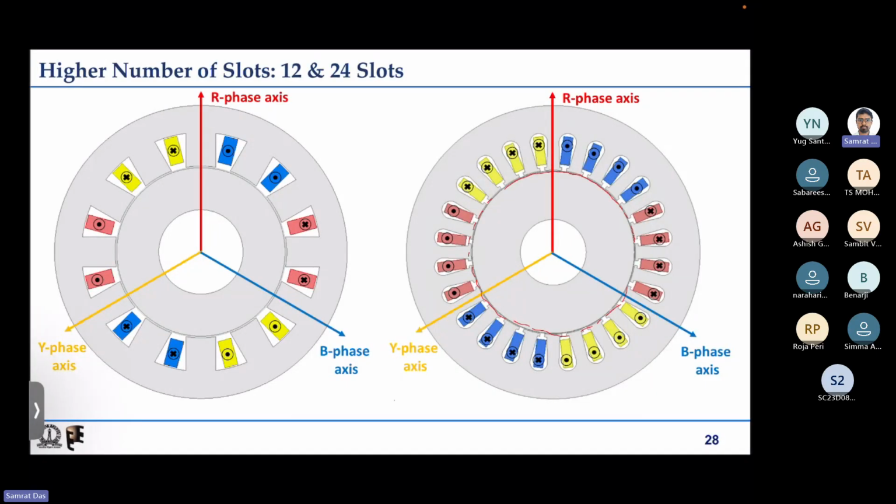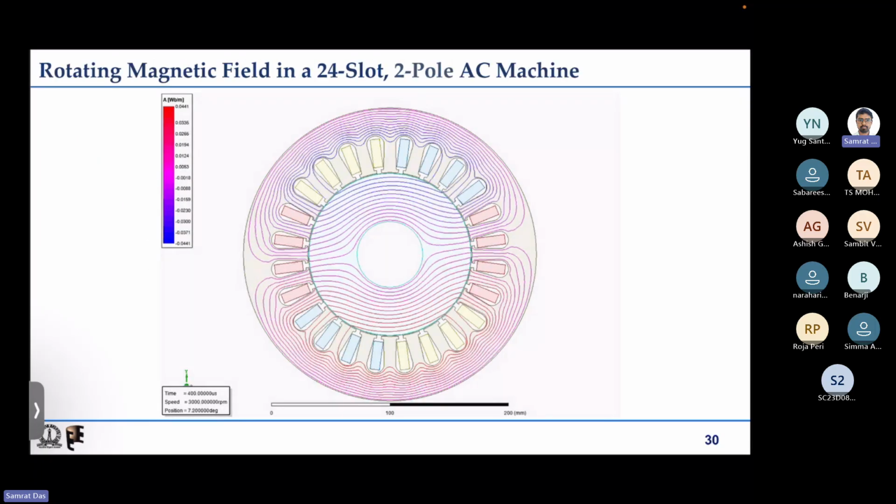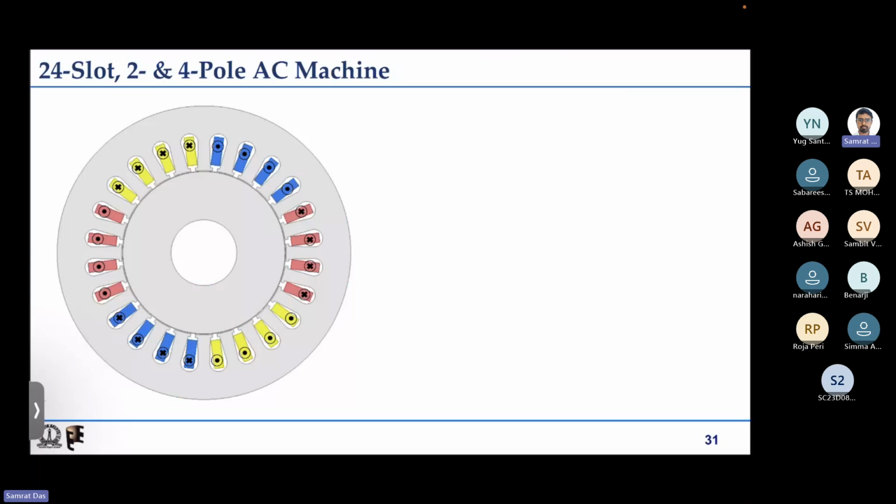through this air gap circle, then if we start from say theta equal to 0 and traverse throughout, we see that we are getting some B distribution which has a fundamental sinusoidal component, and along with that it has certain other harmonics also. So we'll take this example and see quickly how we can analyze this type of structure to see that the B distribution is sinusoidal.